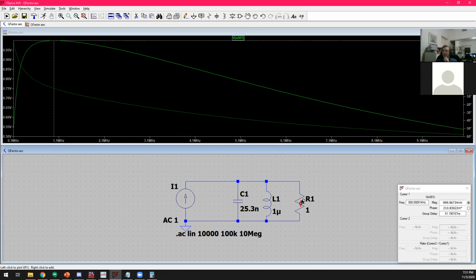So here I have a 1 ohm resistor in parallel with these guys. And that means that this LC tank is super lossy. Like we took our nice perfect inductor and capacitor and we shoved the 1 ohm resistor across them, which will basically suck away any energy that we excite into the circuit, which means that this LC tank has a very low quality factor.